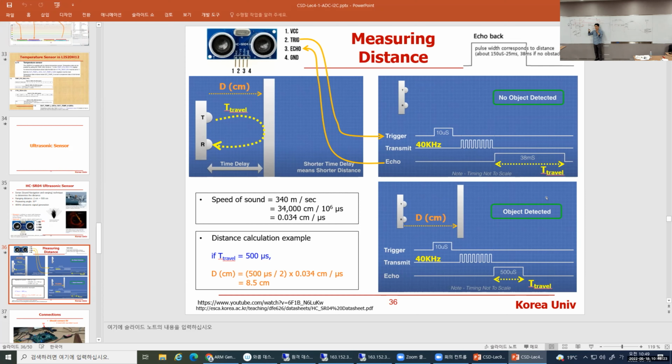You have to do it in 2 places: the GIC interrupt controller, telling it I'm done, and the IO device which generated that interrupt. That is the obvious protocol, done by writing data. Any question about this?